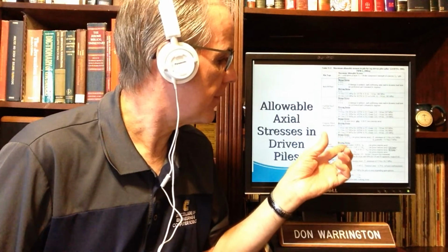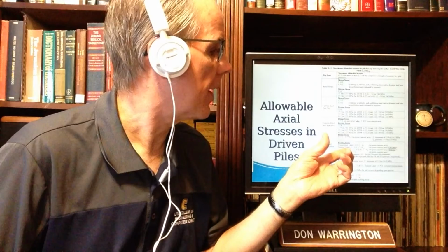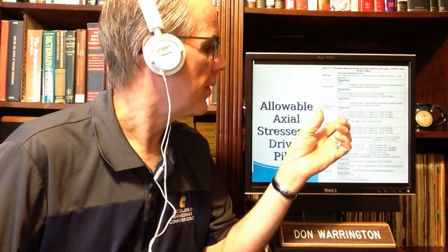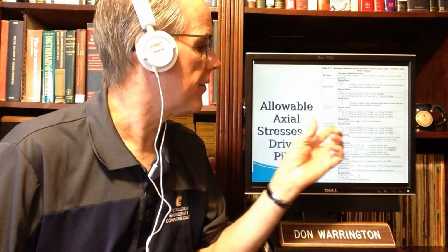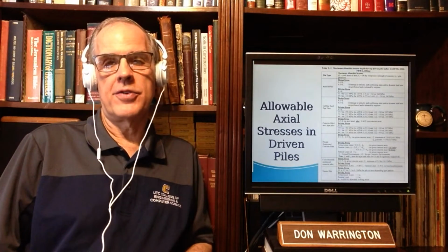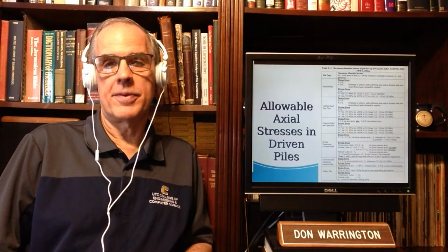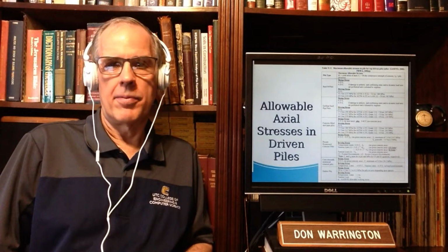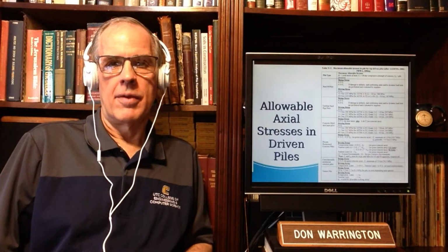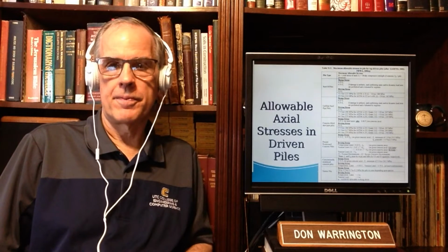And driving stresses are given for concrete piles, for steel pipe, and concrete filled steel pipe piles. Basically, what you do, as I mentioned earlier, even with a mandrel-driven pile, is the same way. You drive the pile first, and then you put the concrete in. Basically, you're driving a hole in the ground to put concrete in, and that's what you're doing with those particular types.